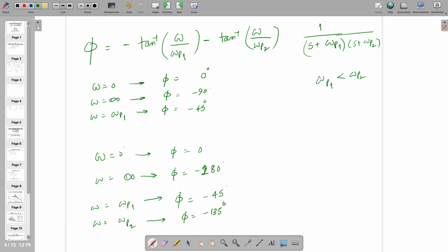So now you have to look at the location of the pole, and you are going to measure the phase margin at the frequency of UGBW or gain crossover frequency. Right? When you are doing this, you can substitute at omega equal to gain crossover frequency, and you can find out the exact number through your calculator. I'm avoiding this because this is part of control theory. Those who are studying control and Bode plots, that's the way they are learning. But these are the information we wanted as circuit designers. So, are you confident enough for this?